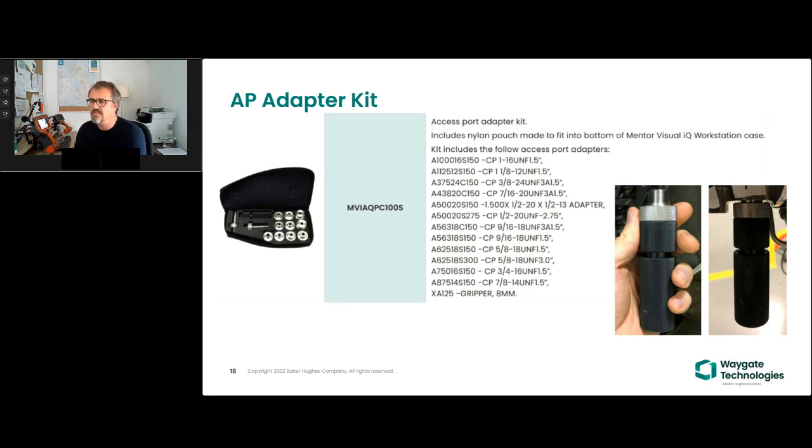The gripper that you'll see holds on and tightens and holds on to the insertion tube, enabling you to essentially perform your inspection. And then when you want it to be held stationary in place, just twist the gripper and you can become hands-free, and both of your hands can operate and interact with the handset, or perhaps with the turning tool, for instance, and allow that footage and that inspection to take place with knowing that your probe is held fixed in place.